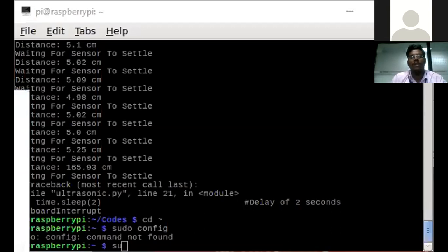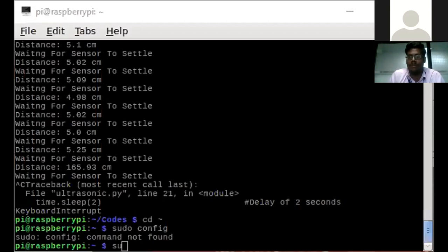So in this Raspberry Pi configuration file, we can see the configuration, how to enable I2C and SPI. So if you use an SD card reader and NFC, other things, they use SPI communication. So we need to first import the SPI communications, and we need to enable it in the configuration file based on the Raspberry Pi configuration. There is an advanced setting. So inside that, whatever protocols we need, whether it is I2C or UART or SPI, we need to enable each one inside these Raspberry Pi configuration settings.